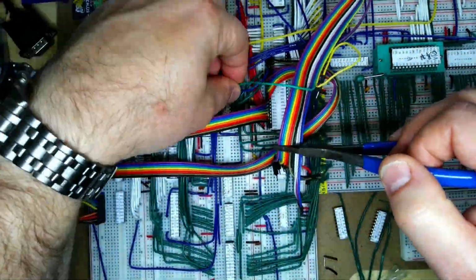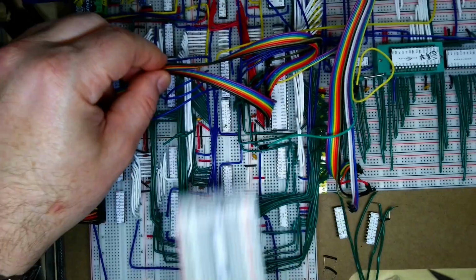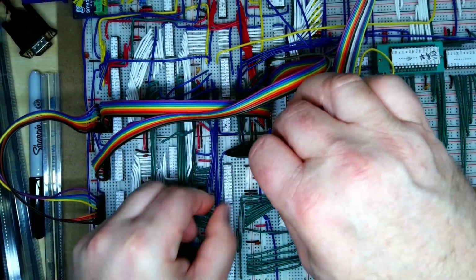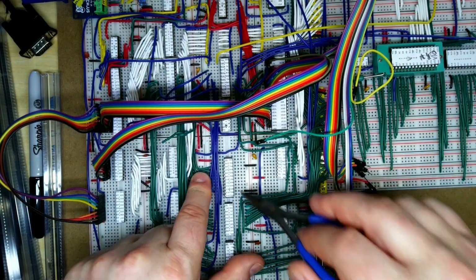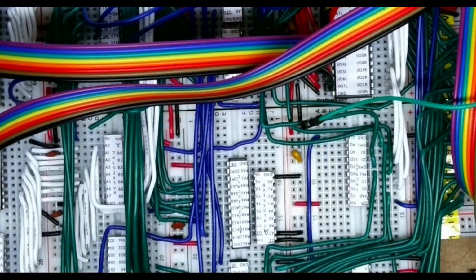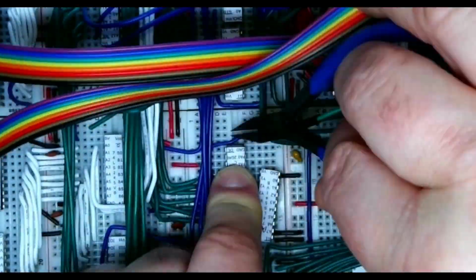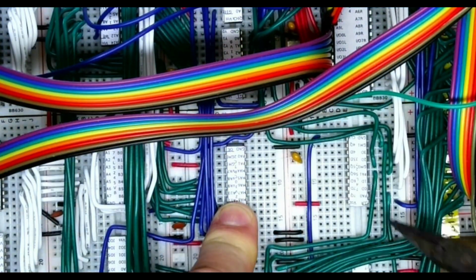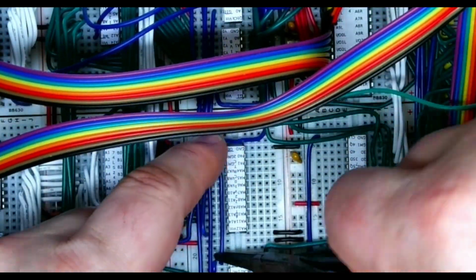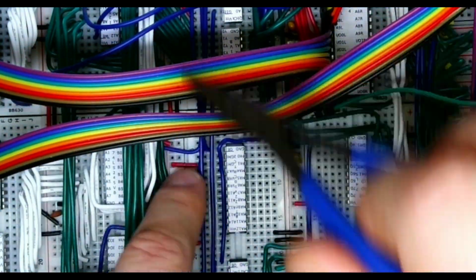So now we're going to take away some of the ribbon cables and put in our new PLD there, take out the original buffer. Just need to shuffle this up a little bit so that the output lines line up with the existing green address lines. So just getting that lined up there. Just need to move that output enable blue line wires just out of the way a little, tidy that up.